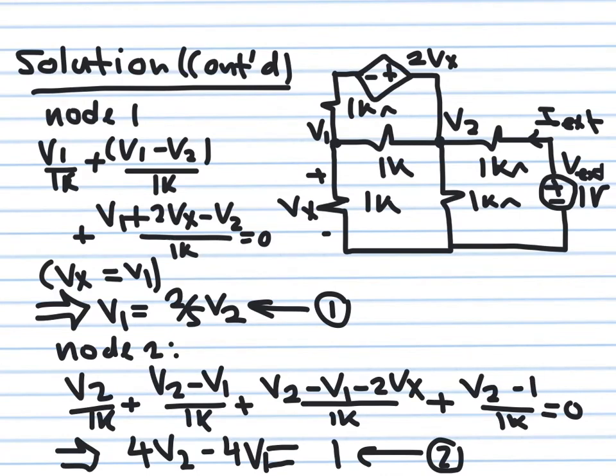Okay, so now we go to part 2. Part 2 is simply to replace the circuit, try to calculate the Thevenin resistance. Okay, so calculating the Thevenin resistance means that you get rid of all the independent sources, okay? And this is what I did. So I removed all the current sources, they are open circuit. I removed all the voltage sources, they are short circuit, okay?